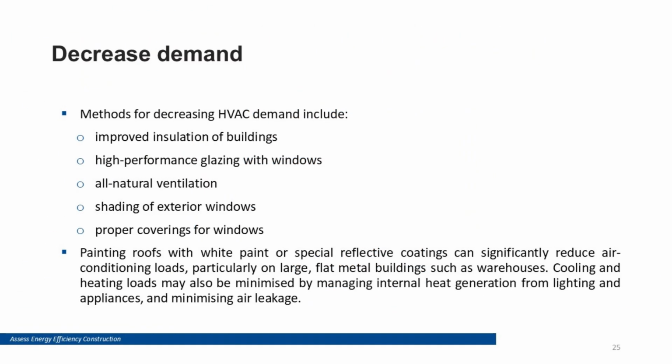Decreased demand. Reducing demand makes everything easier. Practical strategies include better insulation, reduced air leakage, high-performance glazing, external shading, and managing internal heat sources like lighting and equipment. Lower demand allows smaller systems, lower peak loads, and lower running costs.